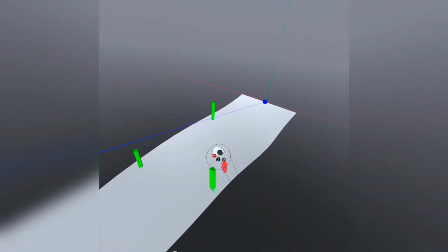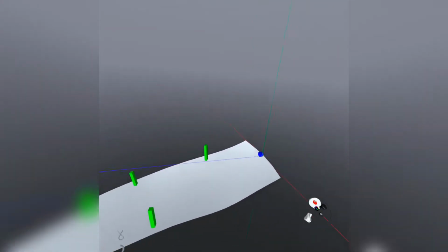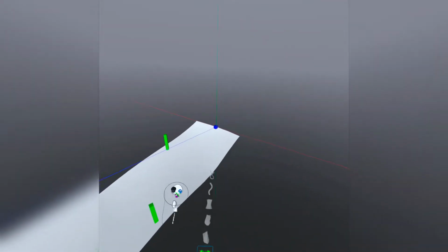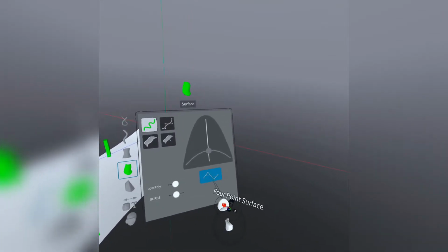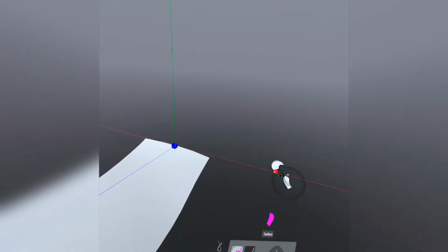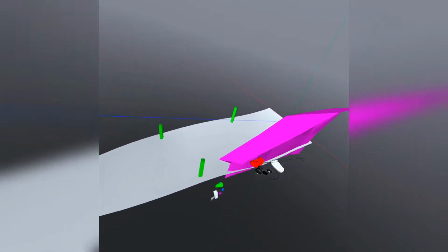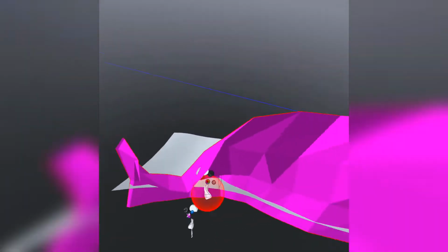And the red color is going to be translated into rocks. So if I want to create a mountain over here to the sides, instead of having this abyss where the player is going to fall, I usually use the surface tool with low poly turned on and the 4-point surface, and I use the red color. Sorry, it's not the red, it's the pink color over here. So if I create a wall like this, I can try to make it different shapes like this into here.